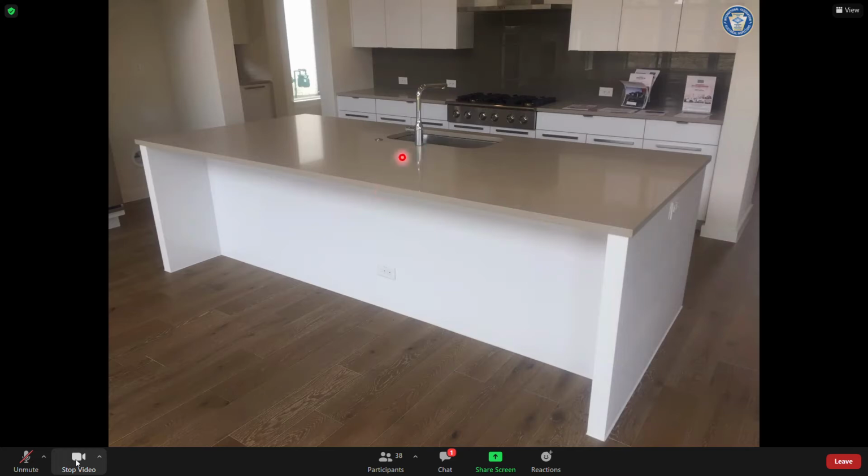Greater than 12 inches right there, looks like to me. Measure 24 or greater here, 12 or greater here. I need a receptacle, and there it is. Again, you see a receptacle that is under an overhang of greater than 6 inches, but that receptacle right there is not intended to serve this countertop. Matter of fact, it couldn't serve this countertop even if I intended it to, because why? It's not within 12 inches of the countertop it's intended to serve.